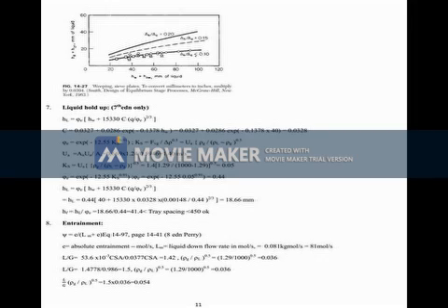Now what we have to get is UH. UH is a velocity. Use the law of conservation of mass. Since for liquid, volume is also okay. For gas, at constant pressure and temperature only, law of conservation of volume is acceptable. Since the temperature and pressure of the column are maintained constant, you can use the law of conservation of volume also. So UH into AH is equal to UN into AN. You know UN and AN, so UH alone can be found out. AH is also known. It is 23.24. HD you calculate. It is coming around 68.7.